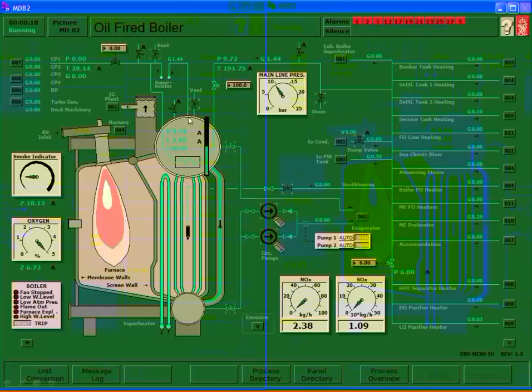You notice there's no valve between the dry pipe and the superheater, and that's very, very important, and it is definitely in all the regulations to prevent overheating of the superheater. What does protect the superheater is steam flow. You want to have every bit of the steam coming out of this drum going through the superheater, because that steam flow is what's protecting it and what's transferring heat.